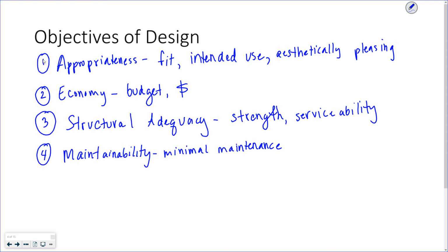A lot of the failures of concrete, in terms of maintenance, is water getting in. There's cracking, water gets in, starts to corrode the reinforcing steel, concrete might pop off. You got what's called spalling. Do you have to do anything to maintain it? So those are the questions you ask when you're designing your structure.